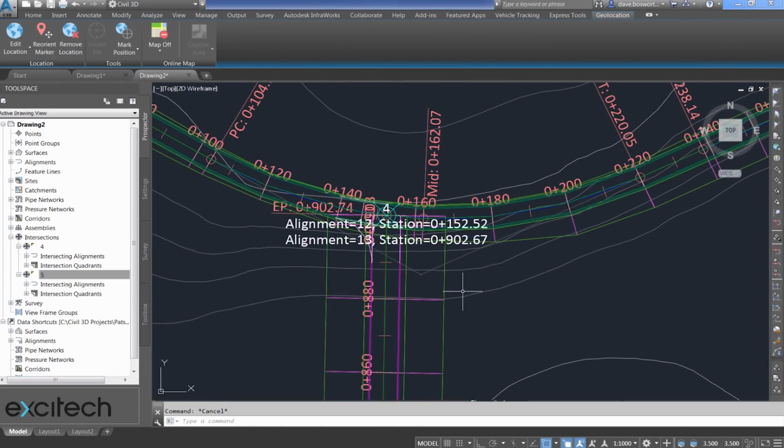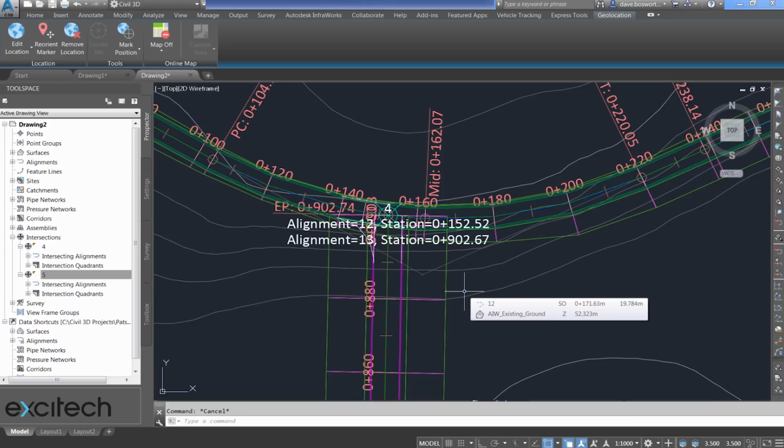So what you'll see here is, although it created the intersection, it didn't fully build the corridor model for it. And I think there may be an issue here with the alignments in InfraWorks not being accurately connected together, and so it didn't build the full junction, but you could of course amend the intersection and rebuild it. So this is a really big improvement in the importing of roads from InfraWorks to Civil 3D, giving us intelligent components that we can refine and edit as we need to.